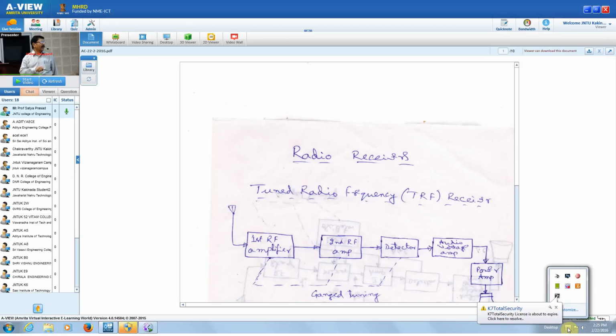So we have the required signal in microvolts. Then if you want, as the output of this second or third stage amplification, an order of volts, what is the gain you require in these two or three stages?